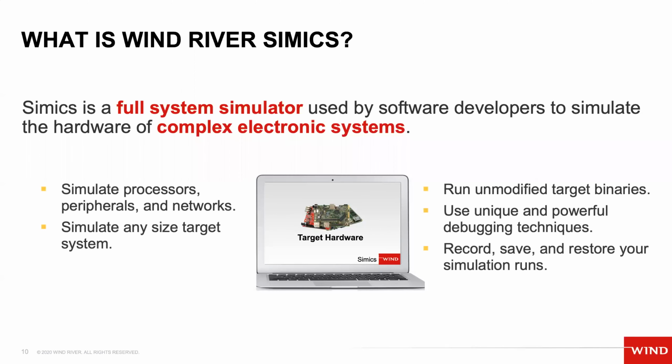And this virtual hardware allows you to do a number of things that you can't do in physical hardware. First, you can test and simulate and stress test just about any size of system. So I could take one simple processor, a peripheral on that processor like my CAN bus, a network of these devices, and I can begin to do things in my virtual world that I can't do in my physical world, like inject problems or record the system state and play it backwards.